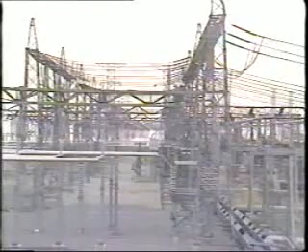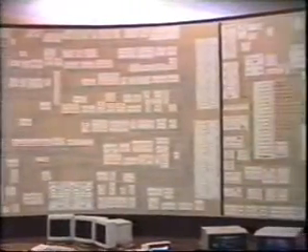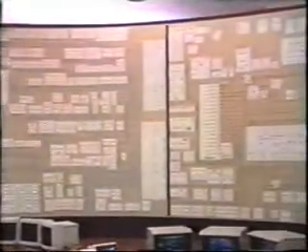Now, just how much system data do we need in order to make a proper diagnosis of system faults and other disturbances? First, you should recognize that we cannot monitor every voltage and current in a particular installation. Many older recorders are limited to 32 channels of information. New digital machines allow 64 channels or even more. Either way, the precise data to be monitored must be carefully selected to get the maximum amount of information after a fault has occurred.